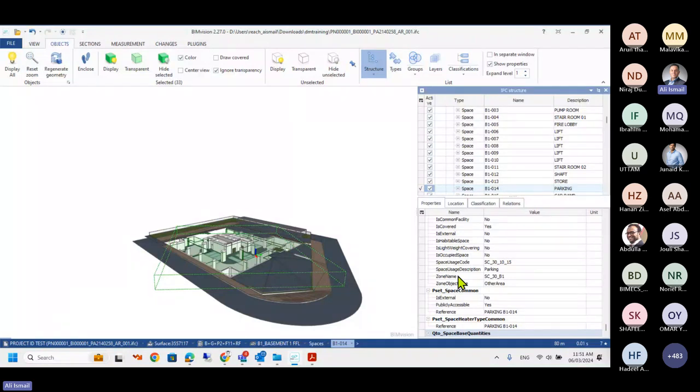So this is the second step that can be done. Install any free desktop viewer for IFC models and try to explore it to see how you can filter, you can extract information, you can create sections in that model and make a federated model. So there is plenty of software like BIM Collab, BIM Vision, and Solibri, as I mentioned. Solibri Reviewer, the free version.